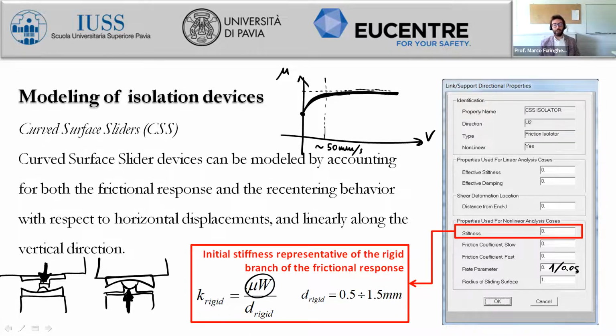Okay, actually, that should be a couple, because we will surely have the application of the vertical load at the same location, because we have the link there. So we should add an additional couple in order to obtain, at the end of all the computations, the location of the vertical reaction displaced with respect to the maximum displacement that we have computed.